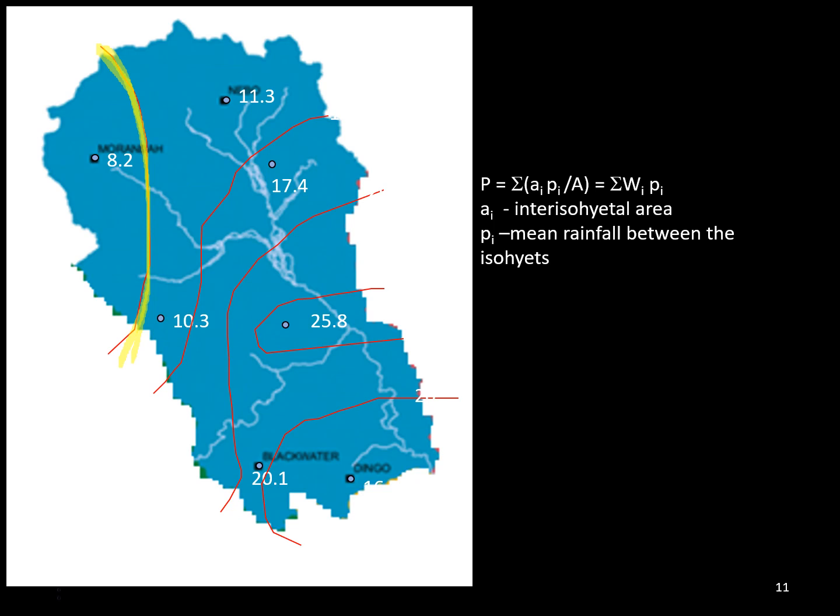so 8 and between 11 there is 10. So you try to draw the contour for every equal value. You start with 0, 5, 10, 15, 20, 25, like that. You can decide any interval. So you just draw the contour line. This is the contour line of 10 meter. Now between 10.3 and 25.8, there are three different values: 15, 20, and 25, right?